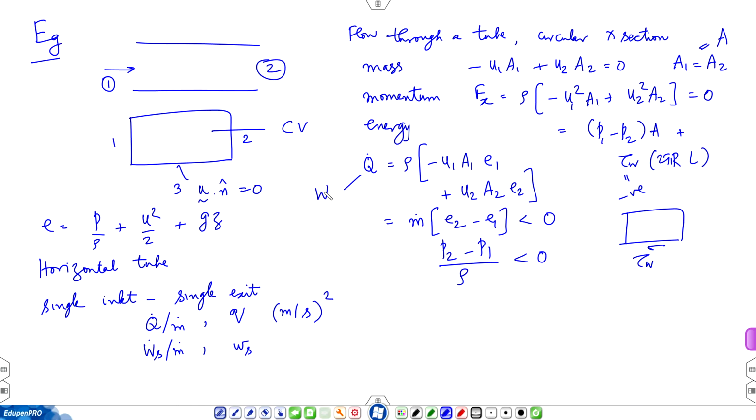So, please convince yourself that these are the units. Now, this q dot arises from internal dissipation and things like that, and this equation q dot equal to m dot E 2 minus E 1 shows that your total energy is lost within the tube. But then what about conservation of energy? It is lost in the sense that the sum of P, u and gravity is getting converted to thermal. The conversion is into thermal, but as far as the mechanical component of total energy is concerned.